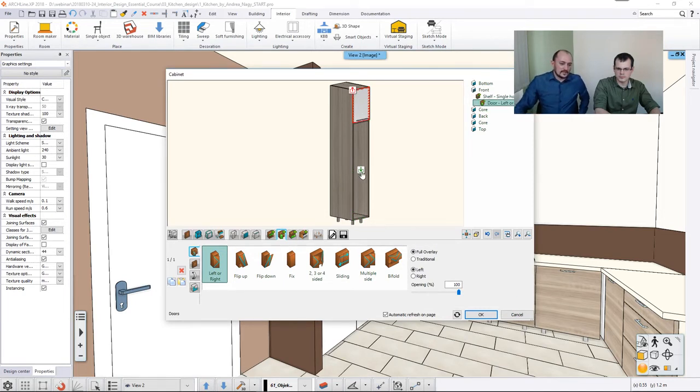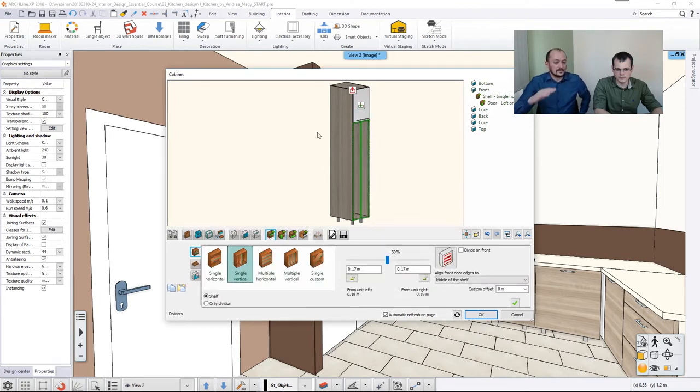And I can actually change between the zones by simply clicking on them. The difference is the color of their icon. The color red represents that I will go into some place where it is already divided or it has already something in it. And now that something is a door because I'm on the door page. So this here does not contain any door, which is very much visible now, but if I go here, I can actually divide it either halfway, or I can set up a value. Now this value, if I remember correctly, should be 0.28.